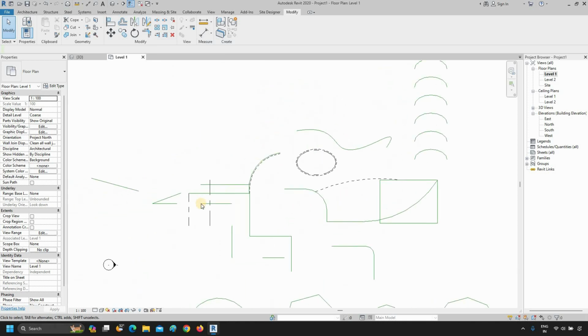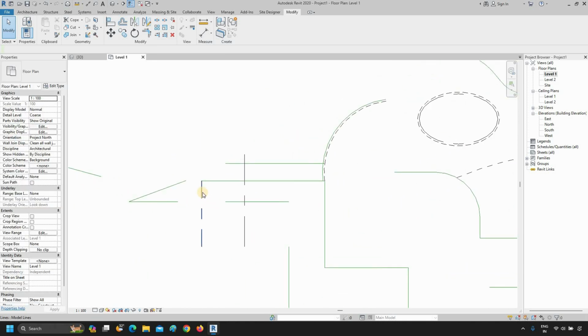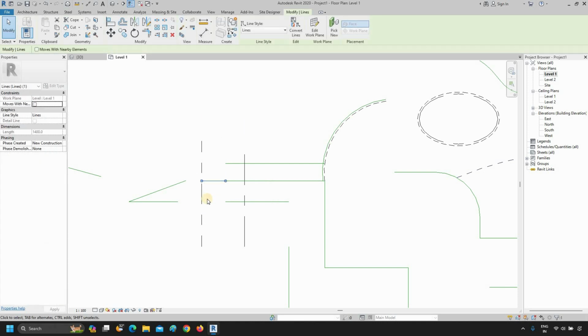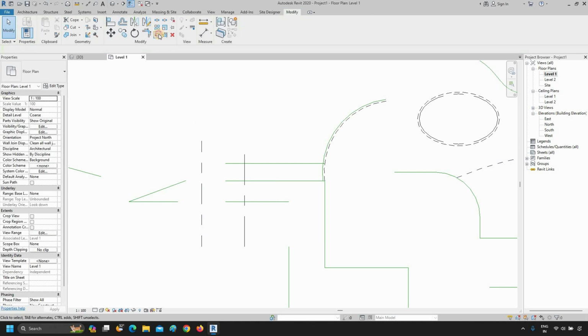Click on the tool. Let's press the center wheel of the mouse and pan the viewport to the other side. Let's extend the reference line. Delete some extra lines. Click on trim or extend. Click on the reference line. Click on the other line. Again, click on another line. Here, you can see the second line is not extended.